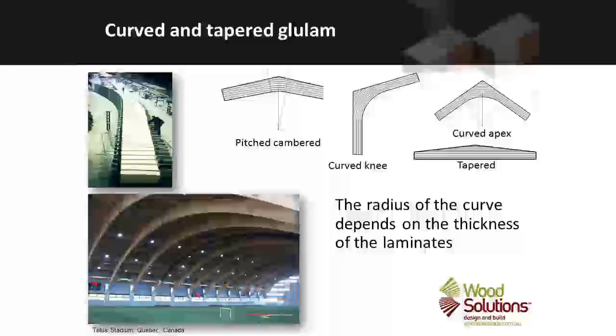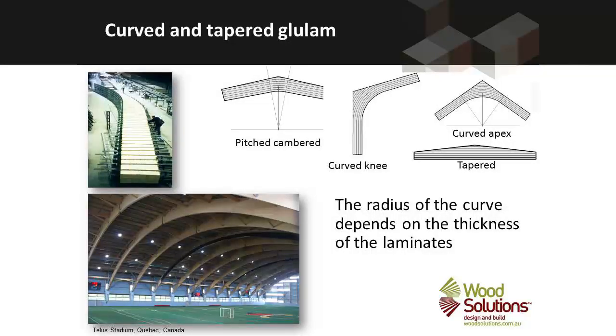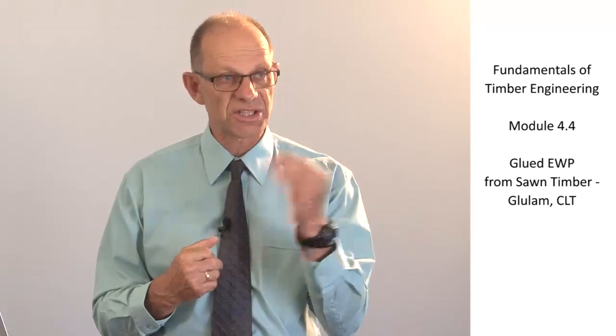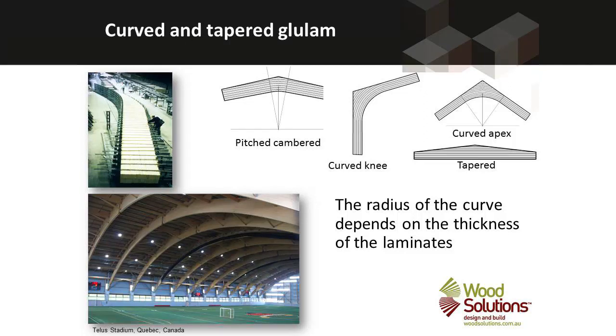Curved and tapered glulam requires special design treatment, so that the curve introduces stresses in the timber, and those stresses must be taken account of in the design process. And Appendix E of AS 1720 Part 1 gives us the tools to do those analyses. But you can see we can achieve quite large spans with curved glued laminated members.